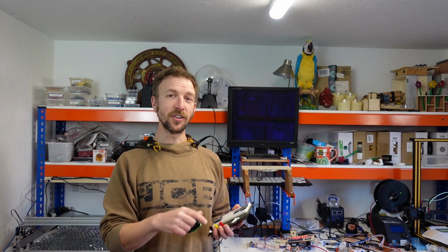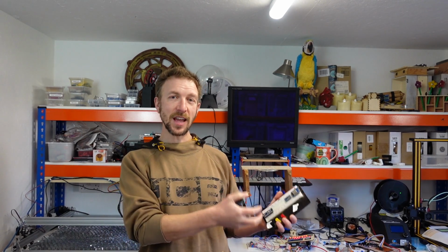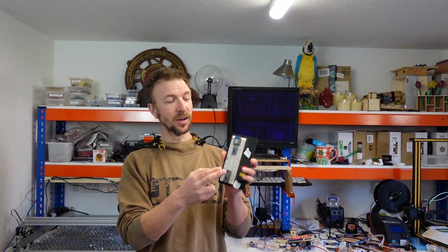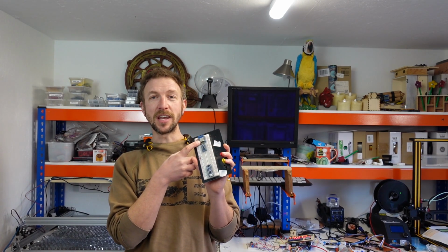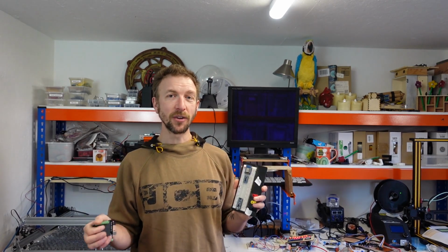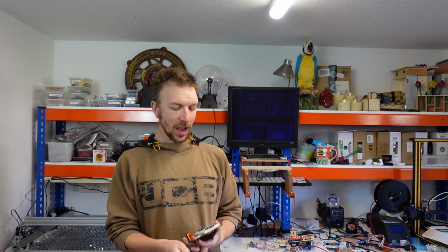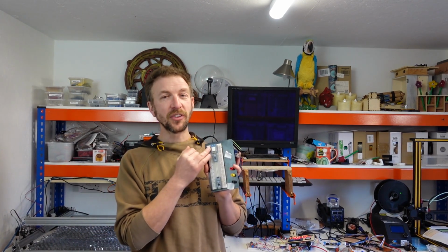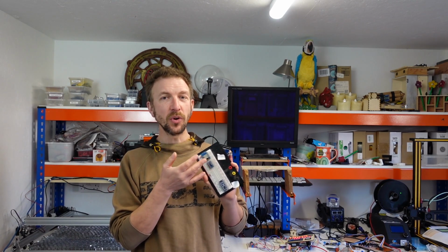So what I could do instead is upgrade all the Nanos in the puzzle controllers to use a 3.3 volt controller like a Wemos D1 Mini. So then I'd have a whole network running at 3.3 volts, and that would work as well. The problem with that is that I've got a load of Arduino Nanos, and they're very reliable controllers for each of the individual puzzles. A Wemos D1 Mini has a load of functions that I wouldn't make use of.